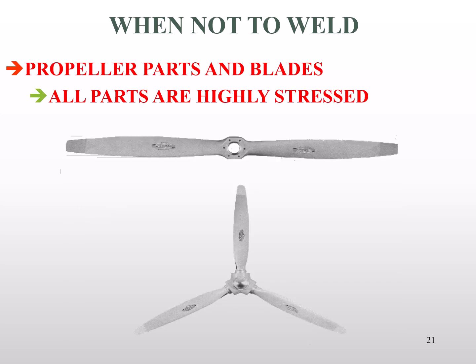Propellers in general are one of the most high stress parts found on any aircraft. Because of these stresses, and there's 6 or 7 acting on a prop at once, we're simply not allowed to do a welded repair. Once again, if it is repaired through welding, it would have to be done at an FAA approved repair station where they have the methods and the inspection techniques to return that part. It is not legal for a mechanic to do that.